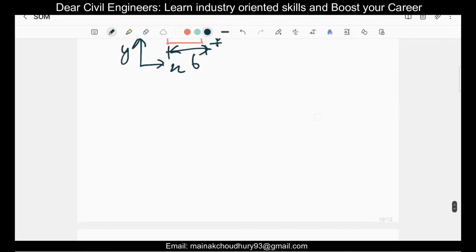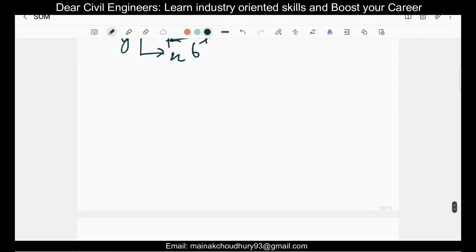Now what happens if we have a different kind of structure? Let's say we have an L section. It is made up of two rectangles, so you have to know that. Let's give some dimensions to this L section, and we can divide this L section into two parts, let's say 1 and 2. These 1 and 2 will obviously have their own B and D individually.